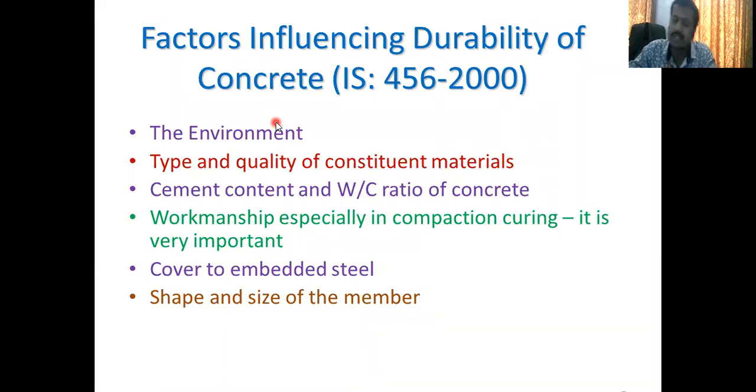Okay, likewise, the same happens with the water cement ratio. If the W by C ratio is accurate as per our mix design, you are not going to face any problem. But if you have taken the water cement ratio much more than what you have designed or what is given in your IS code, then definitely it will hamper the durability. Okay, then workmanship, a very important one.